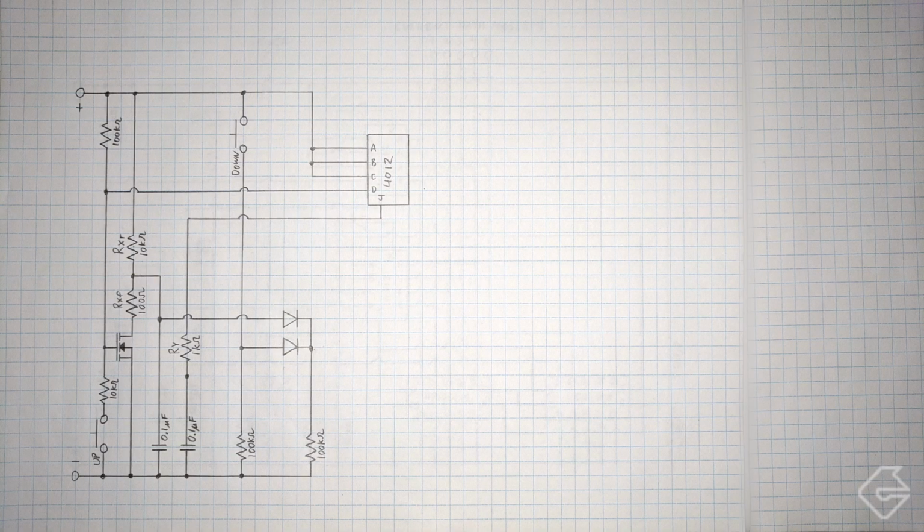So I had to convert these to regular old-fashioned diodes in order to get the circuit to work the way I wanted to. I also added in another resistor over here just to make sure that this diode is discharged when we release the down button. But I still want to see the light. I still want to see when I'm pushing up or pushing down. I just had to wire them in separately.